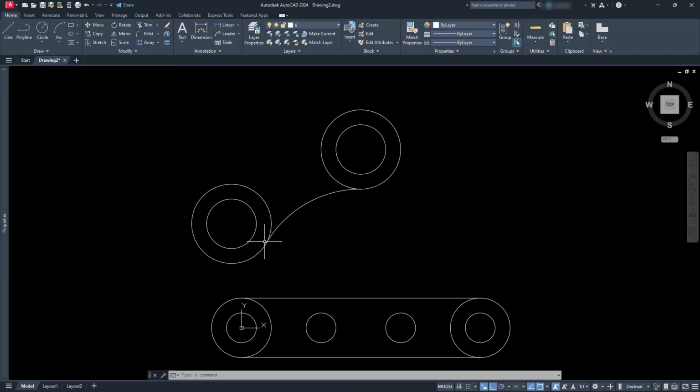I want to show you another option, if you don't feel like continuing to type in and flip between them, you can also use the offset command. So I can go to offset, select the distance is what I'm going to need, and I'm just going to select the distance from this quadrant. So click that quadrant to that quadrant, and that sets my distance. Now I can select this arc and select it here. Go ahead and hit escape.